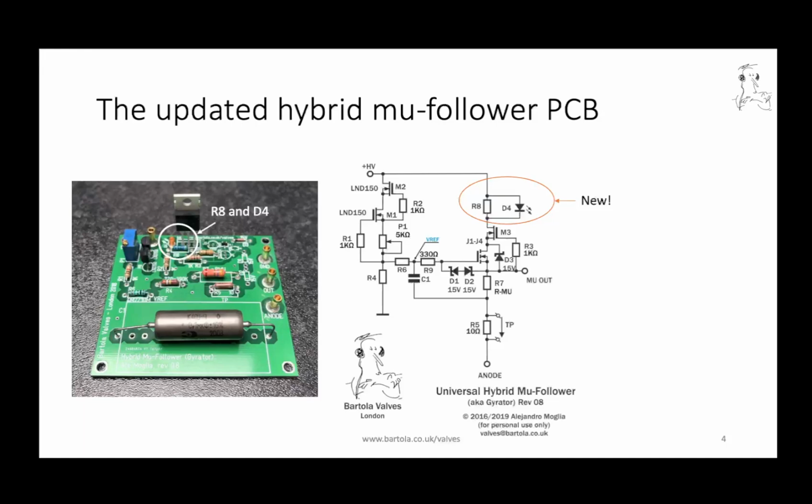And I use carbon comp, 1/8 or 1/4 watt value. That's what you should do. And yeah, the second component is the LED, and you're not required to install it. Most of the cases, you can omit it. Nobody needs to have a visual indication, but if you do, you can add an LED and have some visual indication of the normal operation of the board.